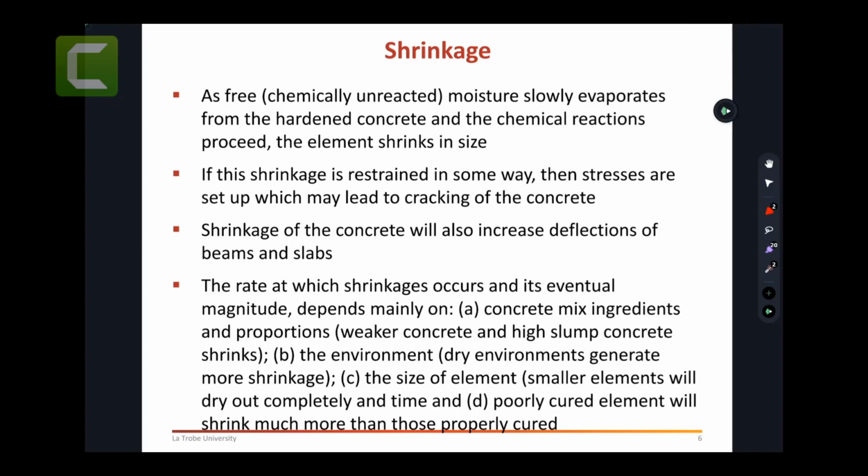That's all what you're going to be doing. Okay, so that comes to dealing with the environment. You're going to see when we teach you how to determine the number of bars, the quantities inside a slab, right? After you find it for strength, you have to go and make a crack control check. That crack control takes care of this point, right? So you're gonna make a small check, and that check will let you think about whether this piece of slab is placed externally, internally, etc.